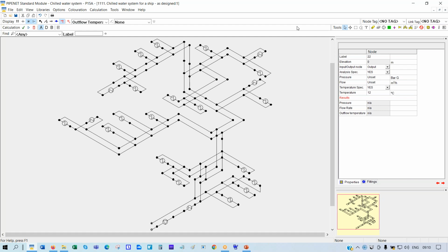In this case, there are two things. I want to make sure that the heat exchangers can get the required flow rate. And secondly, I want to size the chiller unit, which is here. The chiller unit depends on the flow rate and the delta P. So the return temperature is key.